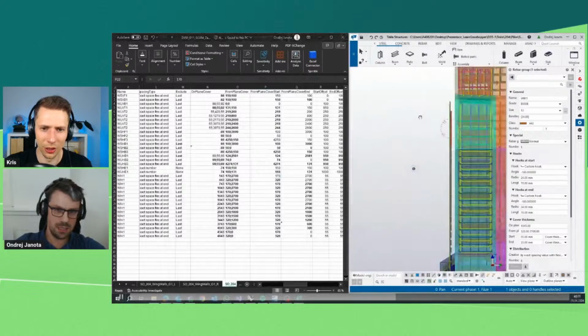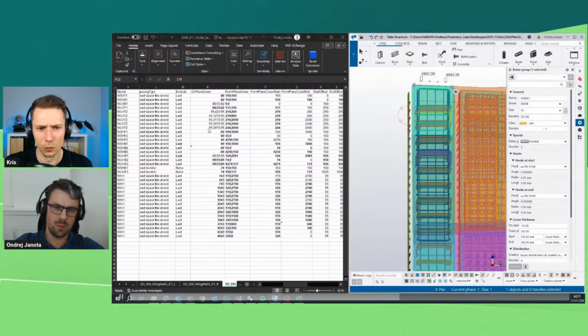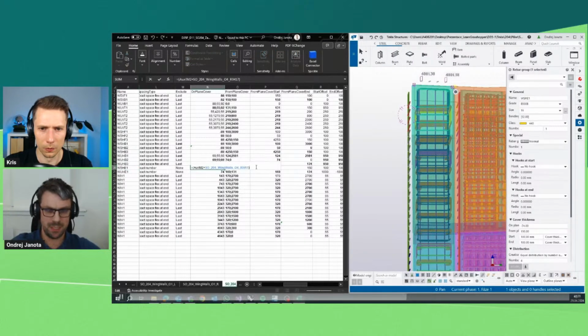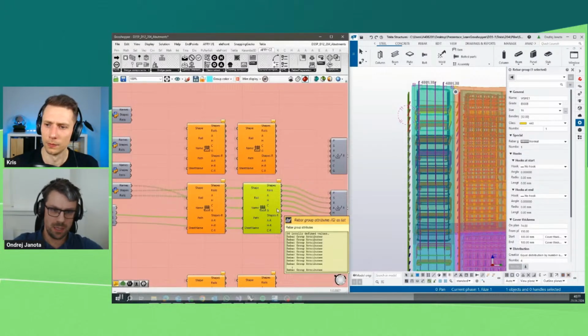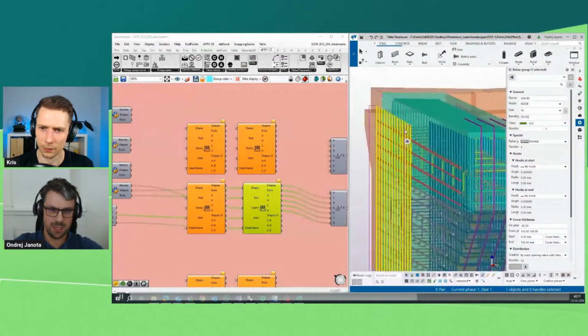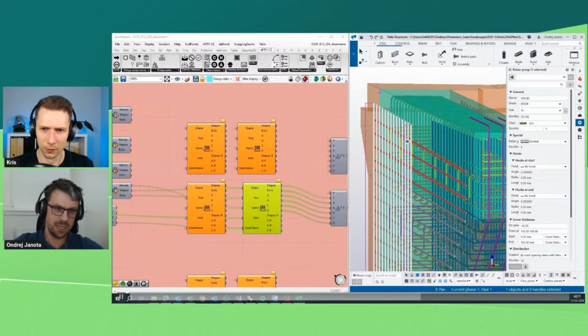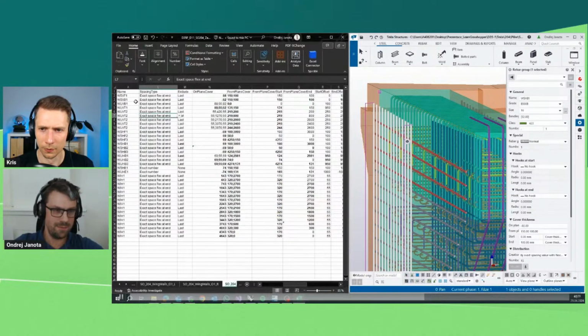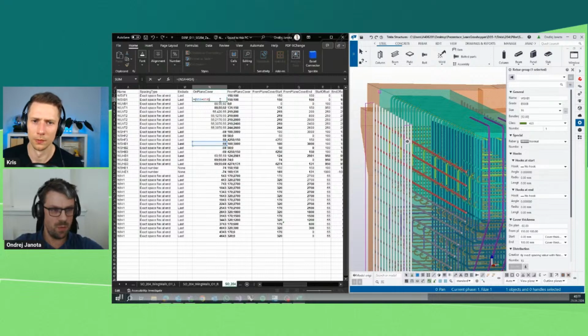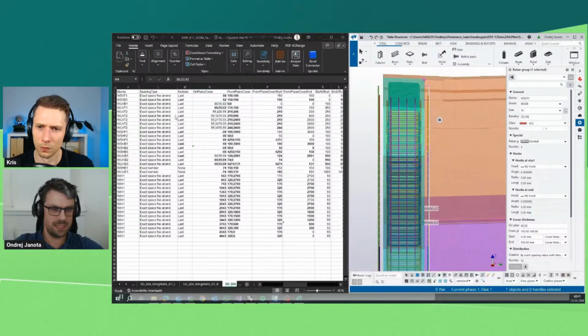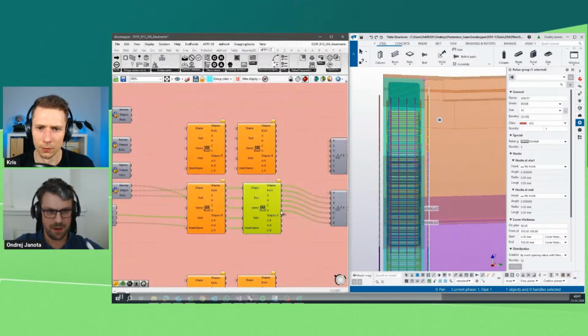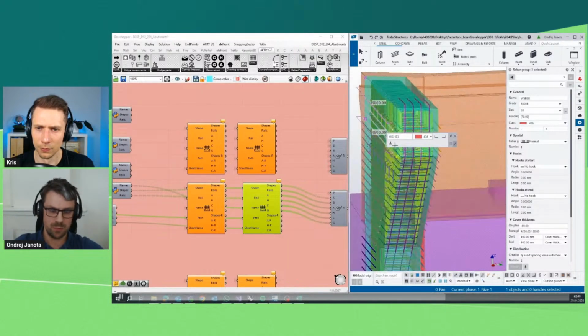Do you have any system for division of the Excel? Well, mostly I divided the Excel as for the parts. For example, abutment is divided into wing walls, left and right, then the foundation and the main wall. But it depends on the designer. Also, the naming convention is very important. I developed my personal naming where from the name you can decode if it's a straight rebar, U shape, L shape, or let's say vertical, horizontal one. But it's up to user.